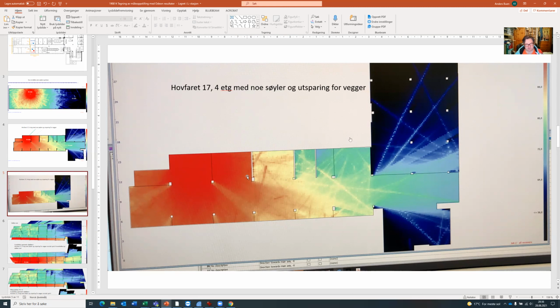So that's a weakness, but one of the strengths is that you get reflections and you model a sort of reverberation in the slab, which you do get. The room acoustics program calculates impulse responses between 2 points, and in this case with the grid calculations you get, for example, sound levels, and this is the maximum levels from a drop here.